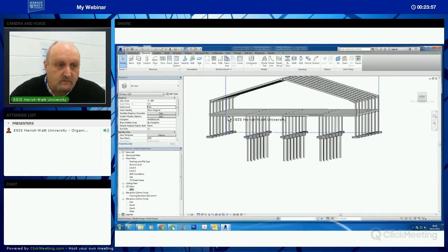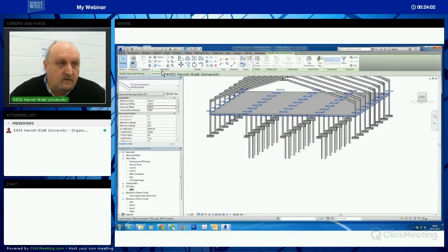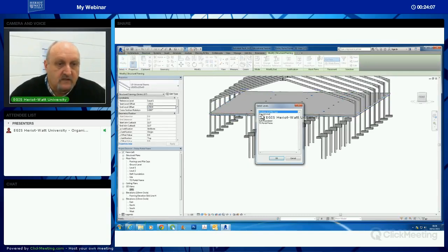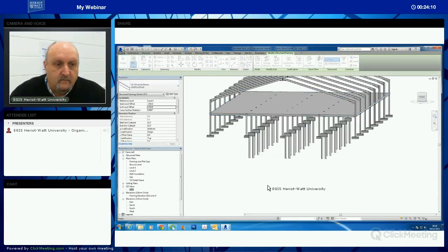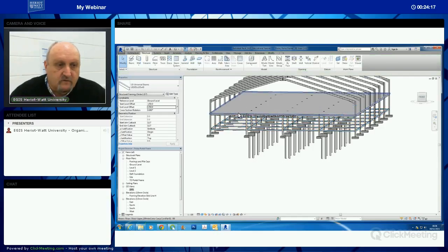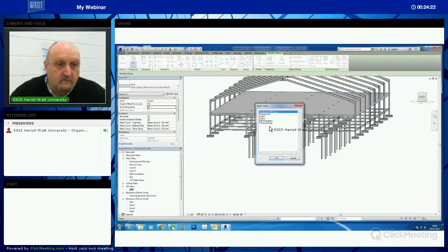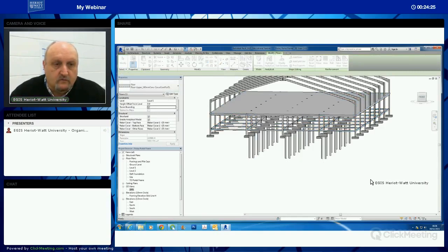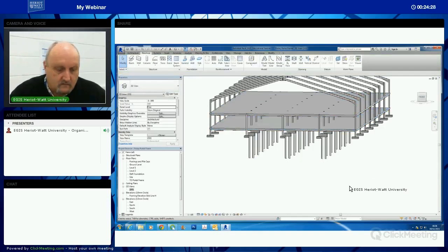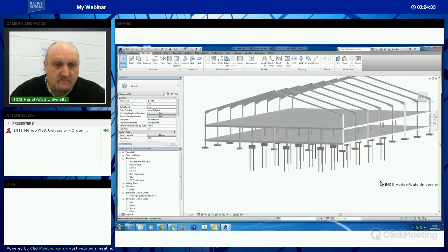I'm going to copy all these beams down. I can select them, SA, copy them all onto the clipboard and paste, align. I'm going to paste them down the way onto the ground level. The offset has been retained, you'll notice they're still at minus 250, and I'm going to do the same with the floor. Copy, paste aligned onto the ground level for the floor as well, and I've got two floors in, and that'll let you see the nice photo frame structure beginning more to emerge. Floors often help these things become more visible.